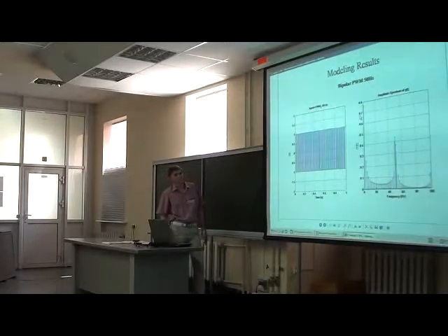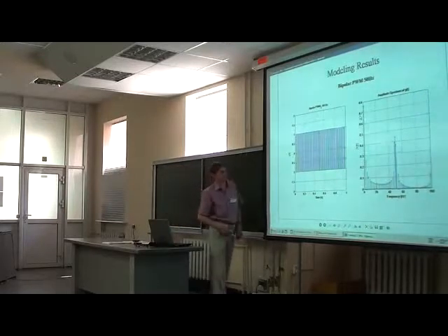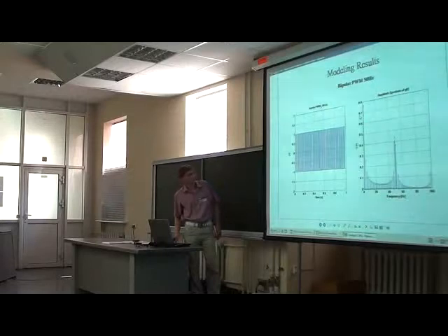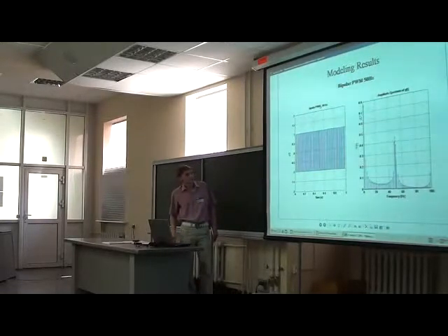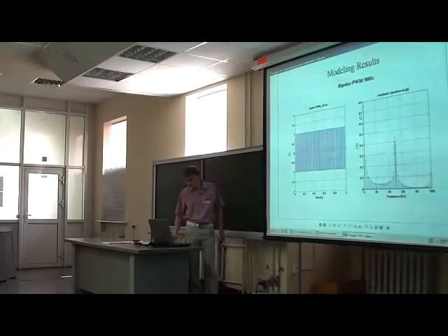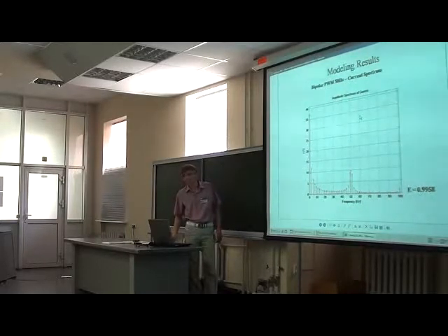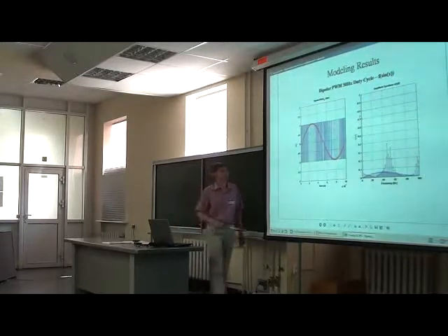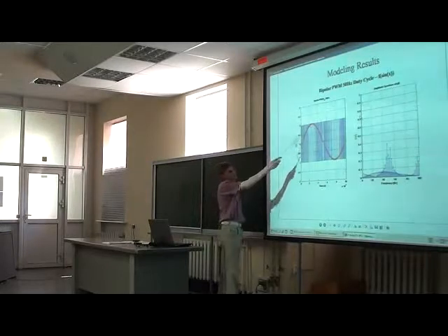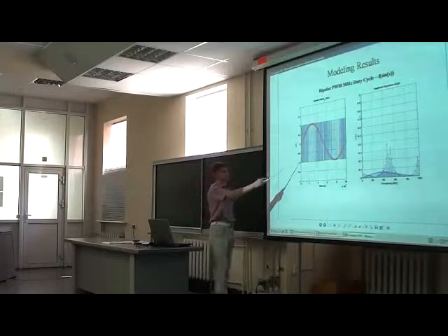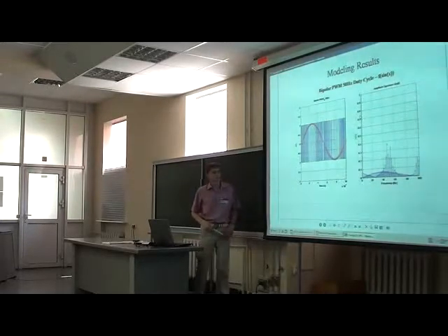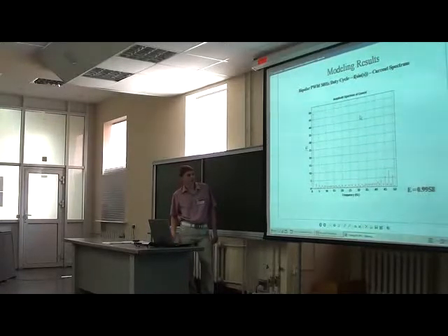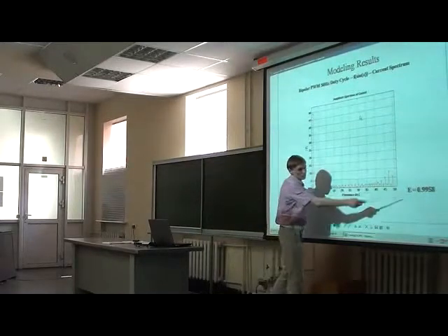And next, we have simulated the bipolar PWM at the frequency 50 Hz. The character is also near to the previous examples. The current spectrum of this signal. And now we change the duty cycle of this PWM signal on the frequency 50 Hz. Here you can see the sine wave. This is just for example. And for bipolar impulses, we change the duty cycle. Here is the frequency domain of this signal. This is the current spectrum of this signal, and the energy efficiency is higher.